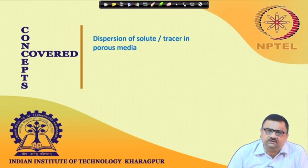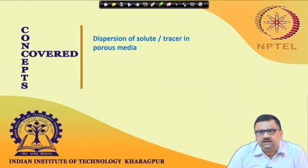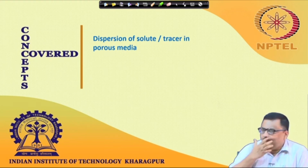And by looking at that concentration profile, with some amount of finesse, we can characterize the porous media, or tell which porous medium is giving more mixing and which one is giving less mixing. So instead of looking at the experimental data, we try to put together certain theories, and we talked about the dispersion coefficient, Peclet number, or the dimensionless time, and those kinds of terms we could arrive at.